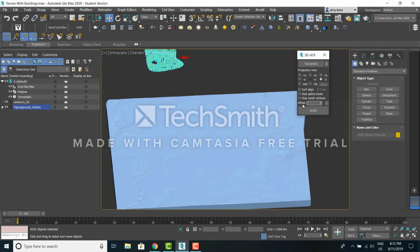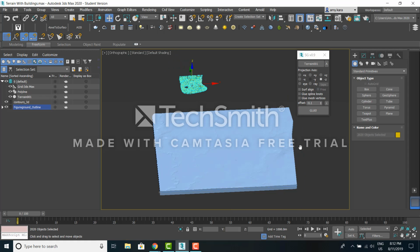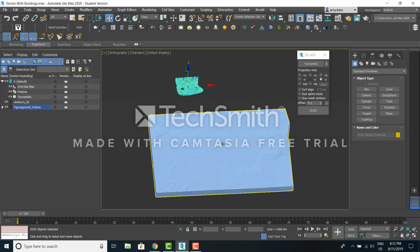So we're going to give it a value of negative, let's say 0.1, and then we're going to press glue, and it should glue the buildings to the terrain because we have the buildings that we want to be glued selected. Give that a moment.